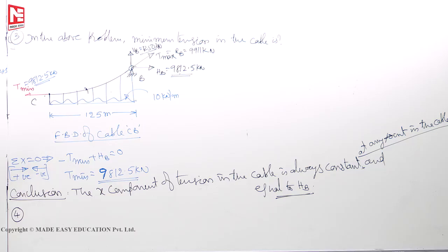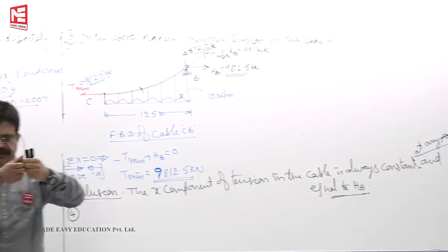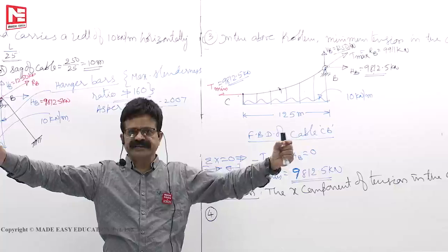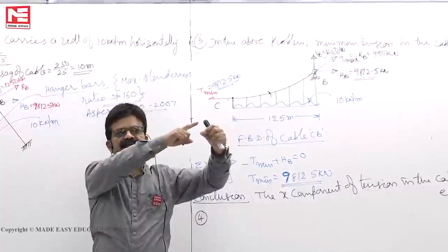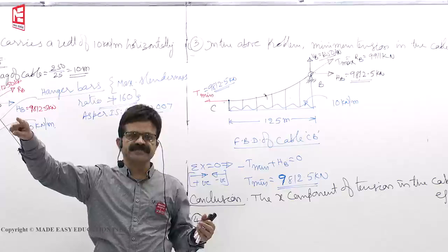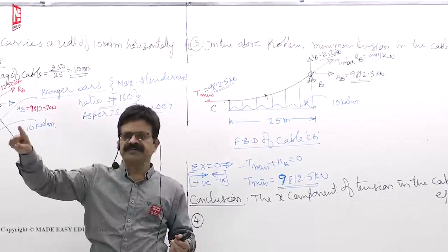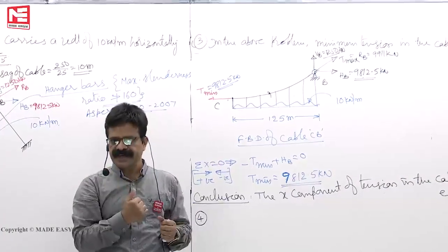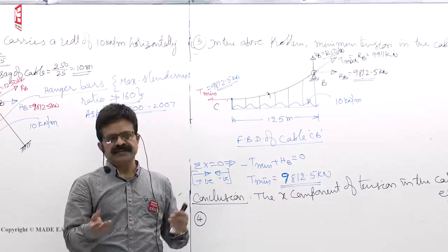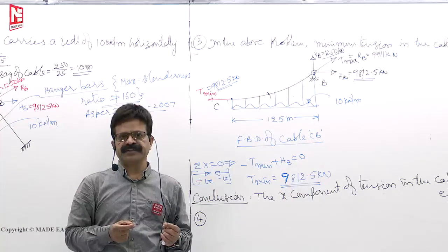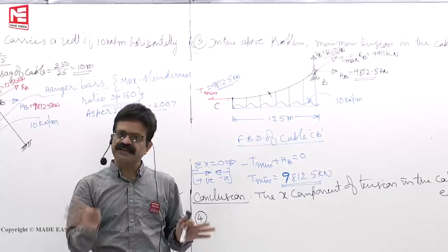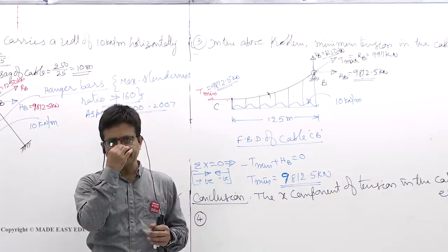When you studied chain surveying in second year surveying, you take the chain, two ranging rods, and you measure the length. If it is hanging, then due to self weight itself it will sag. Straight length and curved length are naturally different, so you have some error due to sag. It is always a cumulative error. If you use the chain 10 times, that error keeps adding. It is not a compensating error, it is a cumulative error. That's what you have learnt.